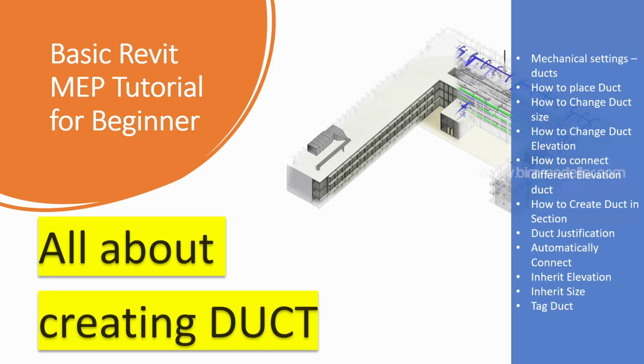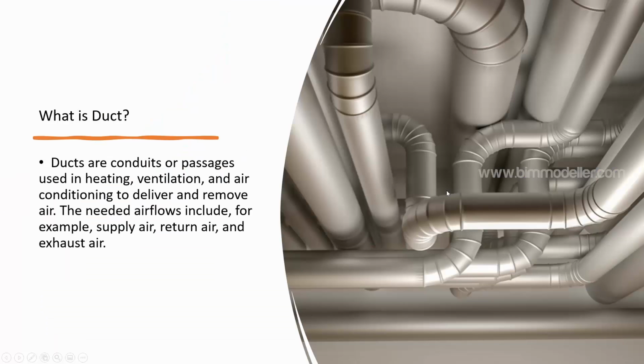This is Raj. In this video tutorial, you'll be learning all the details about ducts: how to create them, what settings and options are available, such as justification, automatic connection, how to use inherit elevation, and how to use inherit size, all these options. First of all, what is a duct?